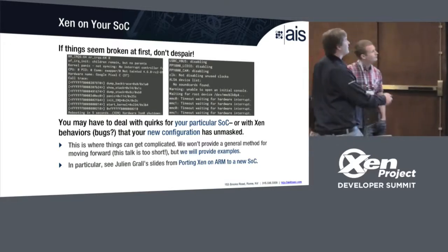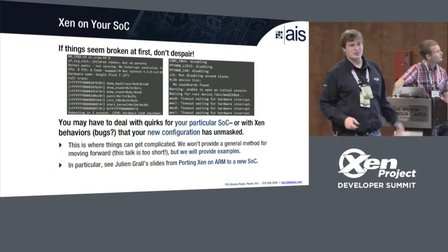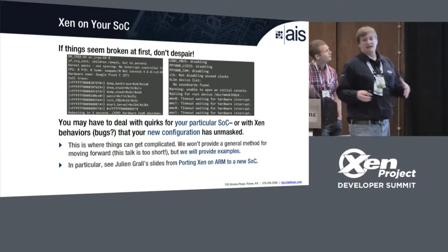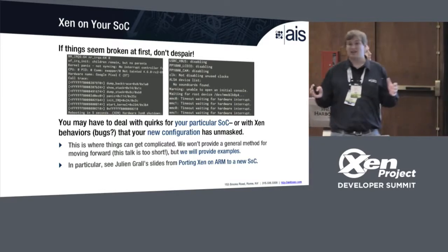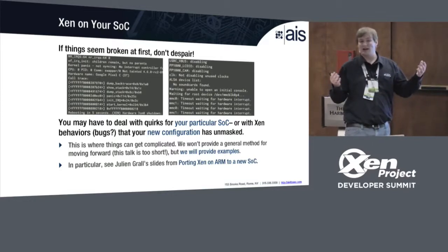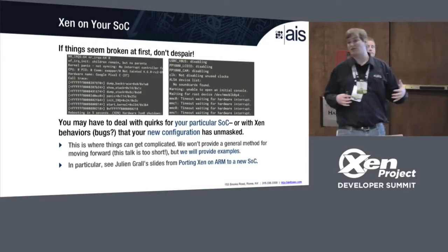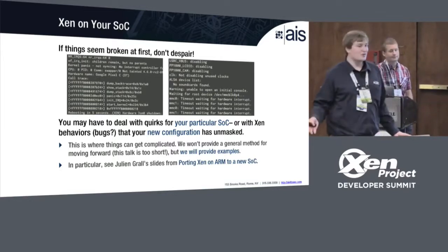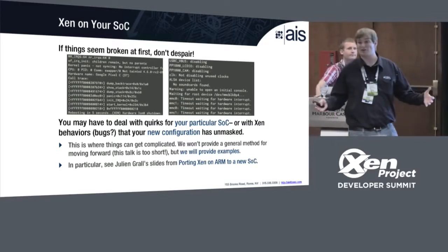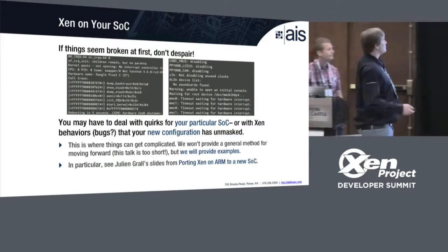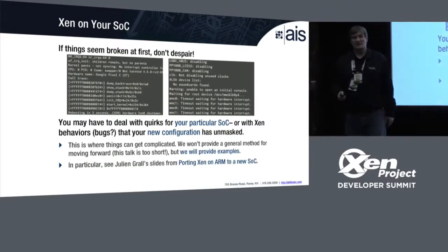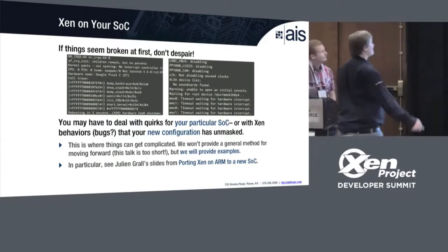I submitted a patch based on the odd bootloader to ship with the Jetson TX1, which actually was selecting that anytime an interrupt happened, it would use the EL1 stack instead of the EL2 stack. So if you bumped up to the hypervisor, it would continue trying to use whatever the stack was from supervisor mode, which causes problems, especially if supervisor mode hasn't been set up yet when you're first starting to boot Xen. Right, so there's no stack. And that just manifests as the whole system just going dark. A lot of fun to debug. So that's been corrected and patched.